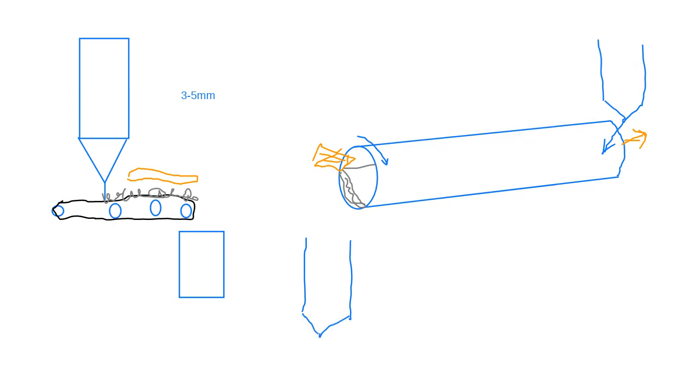And that drops into, well, you will have a rotary valve. A rotary valve is a valve that's got spaces, 4 spaces like that. And this slowly turns, it gets filled. As the empty space is at the top, it gets filled, and then it drops down the solids into a pipe.